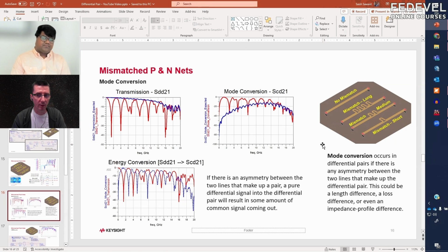Ideally. So when you mention vias, vias can also cause impedance mismatch. Yes, they are usually the bigger culprits than the routing. In routing, you can usually do small bends and all of that, but with a via your reference plane is also changing.